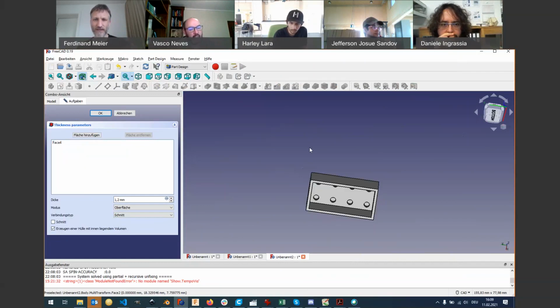Okay, so it has a smaller hole inside. Yeah. Lego pieces actually have vertical walls, which is completely unusual for plastic injection molding. Normally, everything out of plastic has a slight chamfer, whereas Lego pieces are really square. Lego pieces are very amazing. If you look at it from a production point of view, they're awesome. And this was a SolidWorks tutorial that I gave ages ago, and I actually measured a Lego piece, so I'm just replicating what the real Lego looks like.